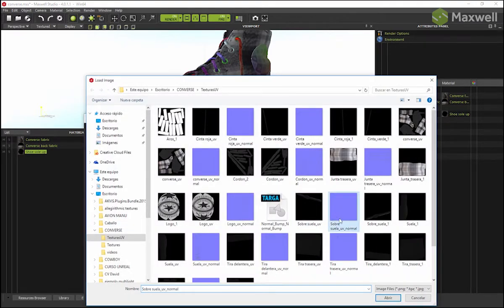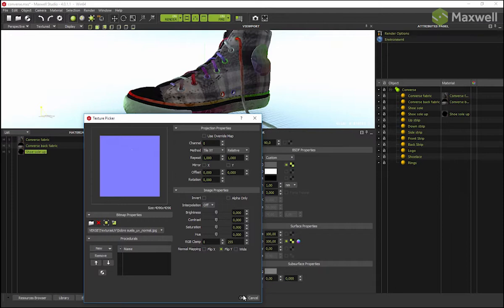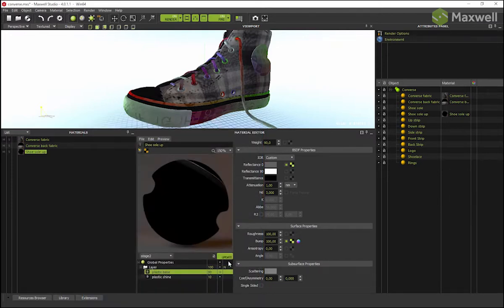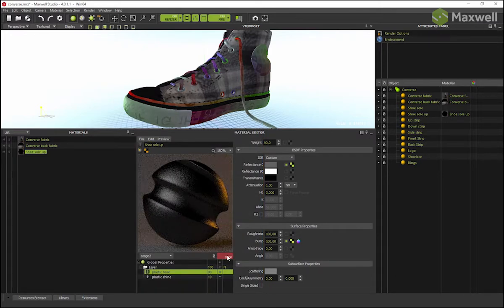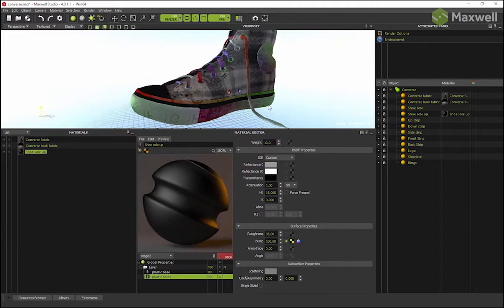The bump mapping allows you to simulate grooves and imperfections on a surface. It only simulates these grooves on the surface. It doesn't actually create the geometry in any way. Brighter values in the texture will create bumps on the surface, and darker values will create indents.